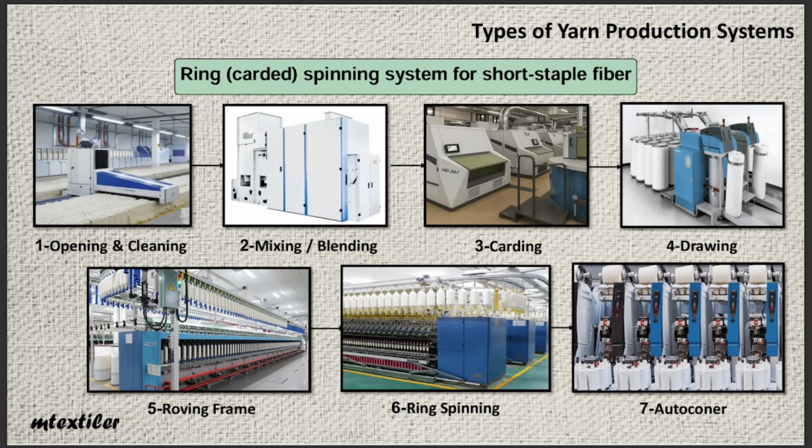The number of bales arranged in this stage depends on knowledge and expertise, and on analyzing the results of raw material tests, the final yarn product requirements, and overall production line review in terms of shade, dye behavior, and the type or breed of fibers we want to blend. Even raw fibers differ in degrees of whiteness, and shade control is necessary throughout the whole production line.